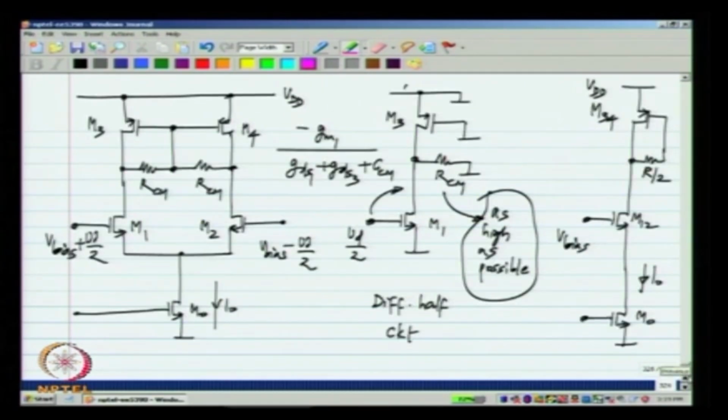So, in a way, what the common mode feedback circuit is doing is shown in this figure on the right. It basically presents a small impedance in the common mode. In the common mode, the transistor M34 is diode connected, whereas in the differential mode you see that the gate of M3 is grounded. So, there is no feedback at all in the differential mode around M3.